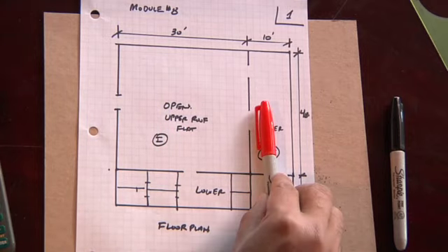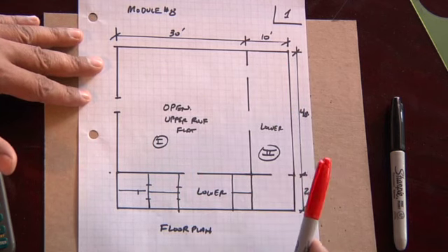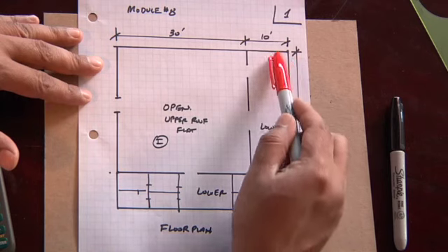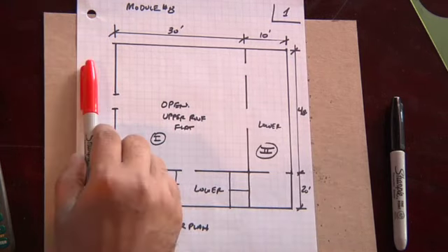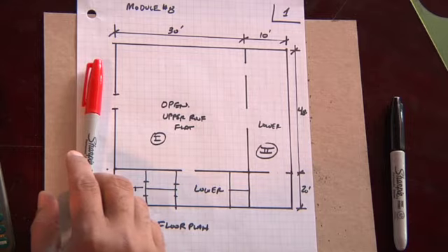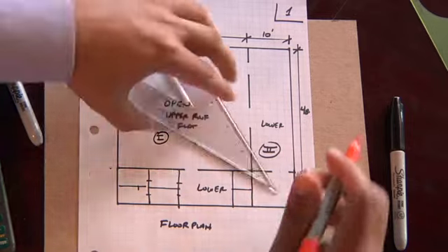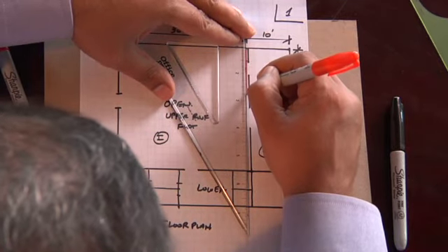So the lower roof plan, if we had to lay out the roof plan for this, how would we lay out the joists? Well, it's really not a difficult problem at all, because when you look at it, your judgment should give you the answer. This is going to be designated as our bearing wall. So I'll use an orange color to outline the bearing wall location. So we're going to make this a bearing wall.